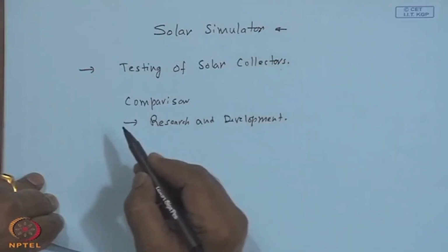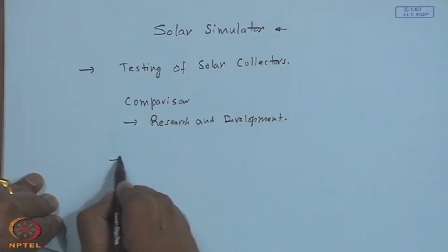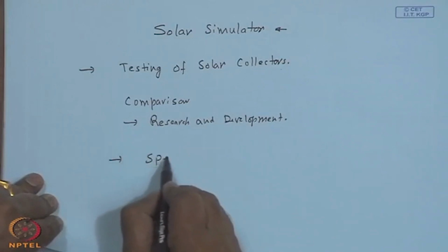If you account for all these things, you may not have more than 200 days of clear days, less than that in fact, to test a solar collector under the recommended testing conditions. So, a solar simulator could be an alternative, but the compromise is spectrum.